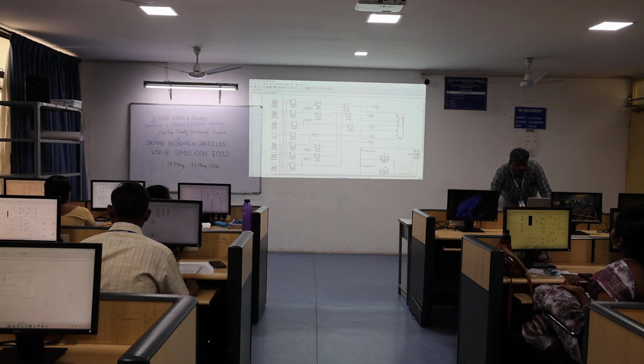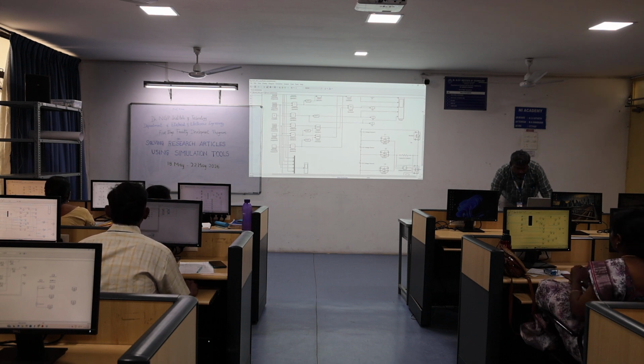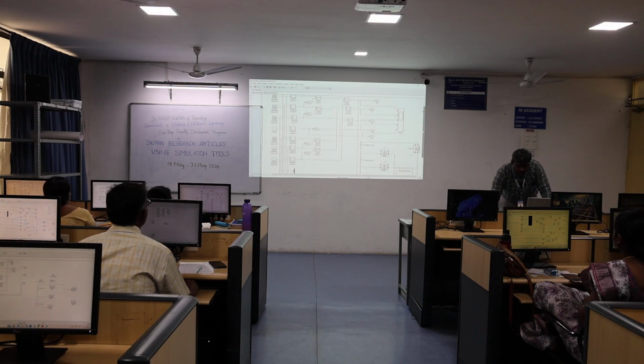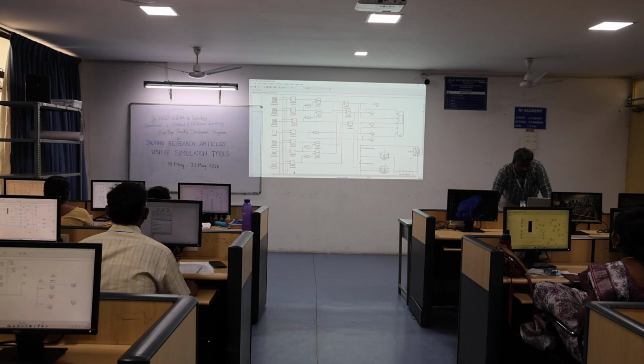Now we move on to the gate pulses. We have already generated the gate pulse S3, the output of the OR gate, S3. Now the gate is connected to S3. Next, again S2, we have already generated the S2 gate pulse from the next OR gate. Then you connect the S2 gate to the S2 switch.